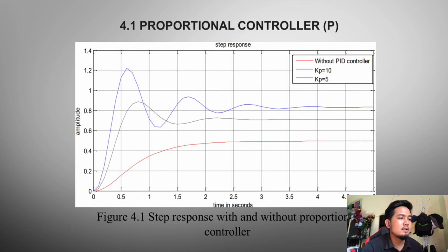The high overshoot, settling time and steady state error necessitate the integral and derivative parts to be added to the controller, as not all of the design requirements can be met with a simple proportional controller.